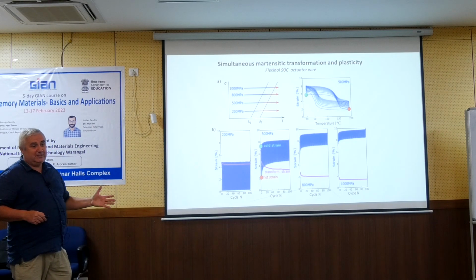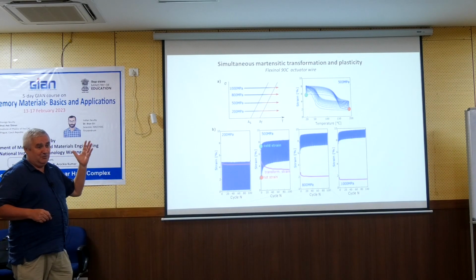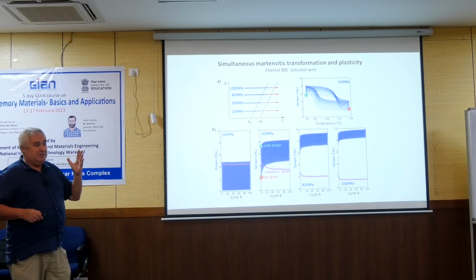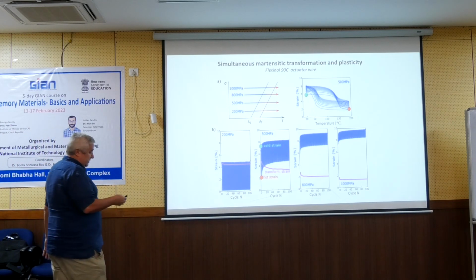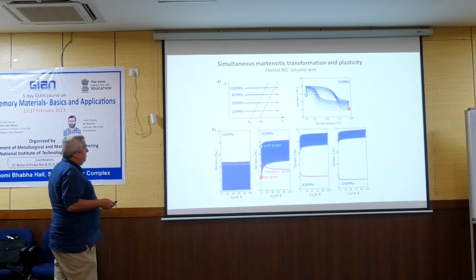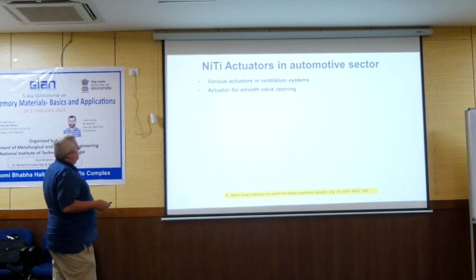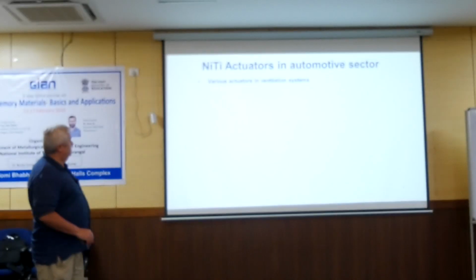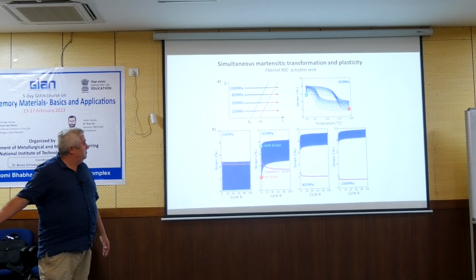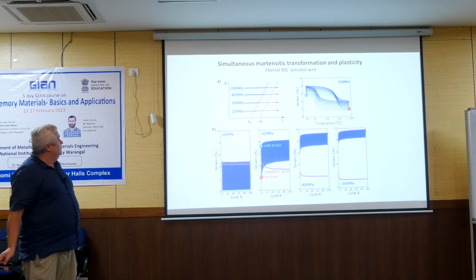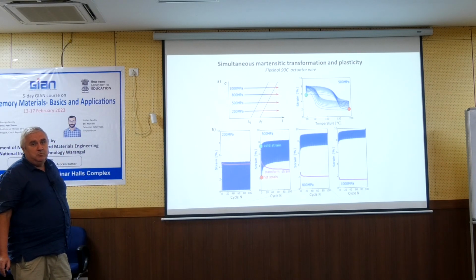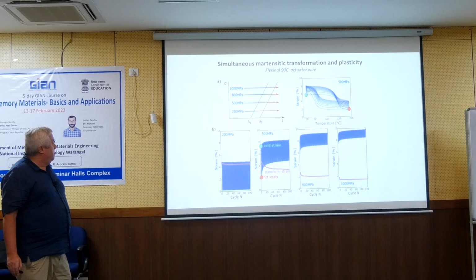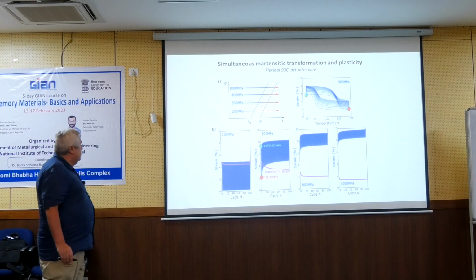They will always tell you, if they give you the wire, maximum stress 200 or 150 or 300, but they don't tell you why. And there is a very good reason for that. So what the previous slide implies is, if you want to load it to a higher stress level, you have to reduce the amplitude for it to work for a normal cycle. Is that what it has been done? These four graphs.